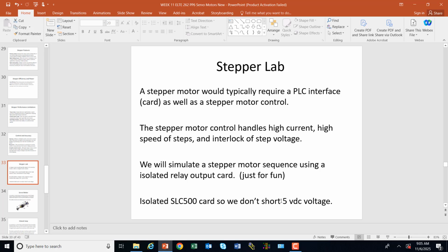And then in this lab, I've also got a linear potentiometer, a voltage divider, that we can incorporate when we take this stepper lab to make linear movement, to then verify that the stepper motor is producing linear distance or linear velocity that matches what we want.